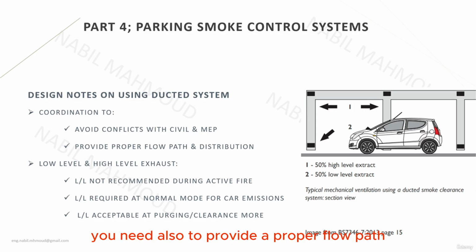You need also to provide a proper flow path and distribution, which means that you need to provide extraction or exhaust points at low level and at high level at the location of the car parking slots, and you need to achieve a proper distribution to prevent any accumulation of smoke or pollutants like carbon monoxide.